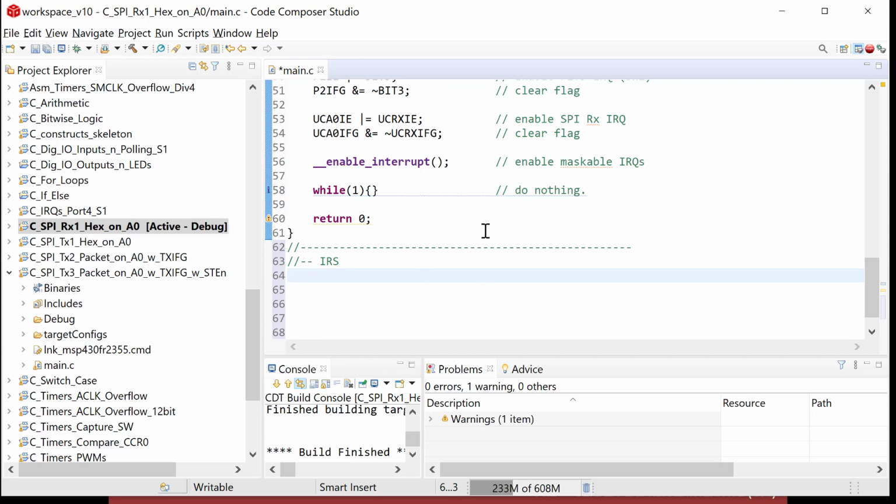Okay, so if I press button 1, I want to set up an interrupt that does this. I'm going to go pragma and tell the compiler, excuse me, please set up the interrupt vector table for port 4, please, and its name is vector. And go ahead and put the starting address of the next routine into that vector.